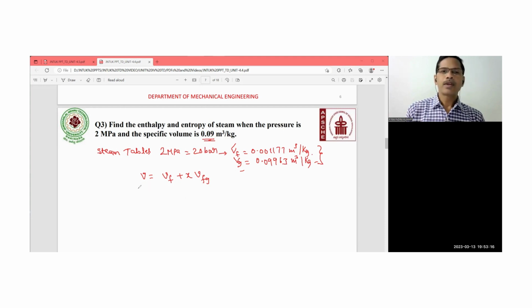So this v, 0.09, is equal to Vf, 0.001177, plus x, the dryness fraction, which you have to find, into Vfg, that is Vg minus Vf.